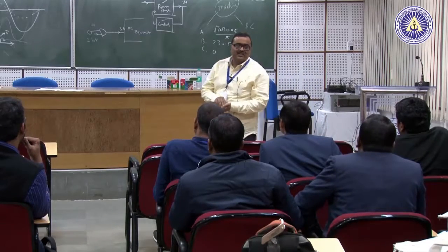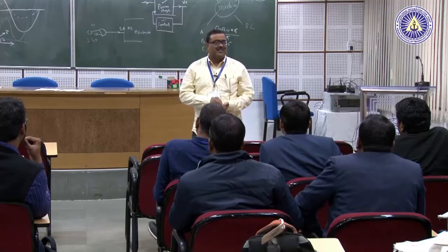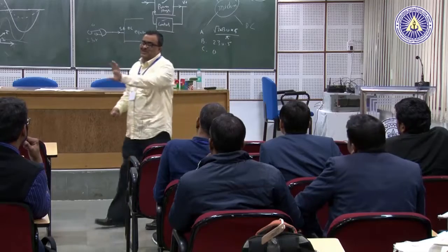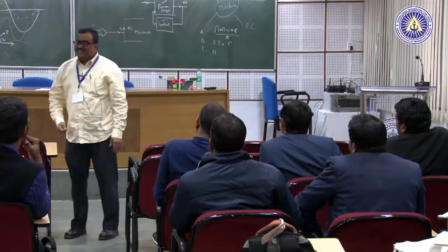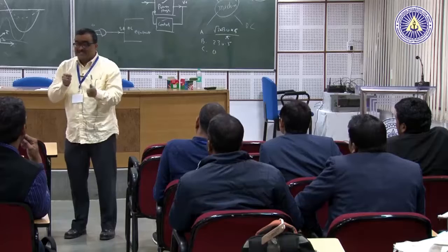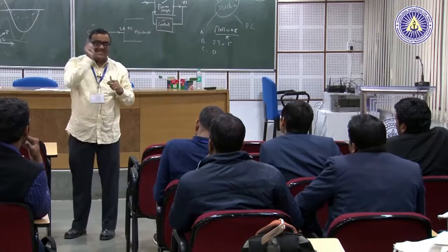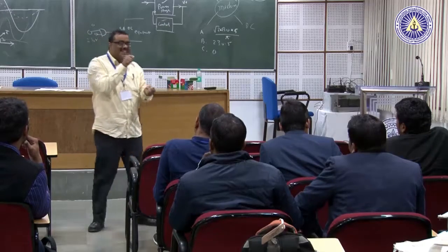Transformer. Why transformer? Because it eliminates DC, it does not couple DC. Yes, so it comes through a transformer, and the transformer will take away that DC. That is why every time I measure, even though no one is around to see, because it comes through a transformer, my DC has been taken out. I will only see AC.